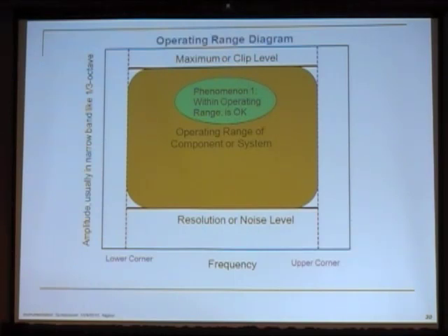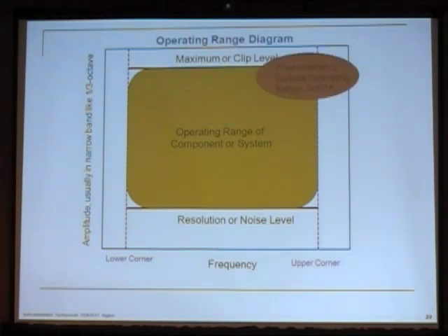But you can define that range, and then you have to look at what you want to measure. Am I measuring static strains, quasi-static, dynamic? If I'm measuring ambient vibrations of a bridge, or ambient strains from vibrations of a bridge, it's going to be very different than if I'm pushing with a static cylinder. So the basic idea is that you define your phenomenon, and if it's outside the operating range, you've got to figure something else out.